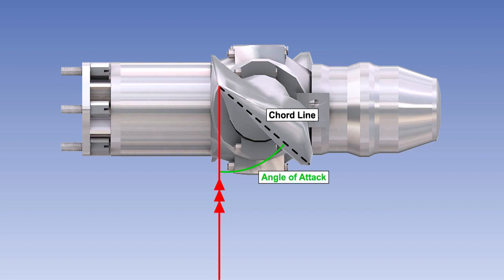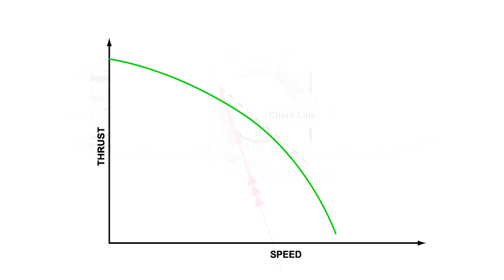When the aircraft is stationary, the airflow relative to the propeller is from beneath, as shown. However, as the aeroplane gains forward speed, more of the airflow comes from the front, and as a result, the angle of attack and subsequent lift produced will decrease. So, similarly with the jet aeroplane, a propeller-driven aeroplane will experience decreasing thrust during the takeoff.